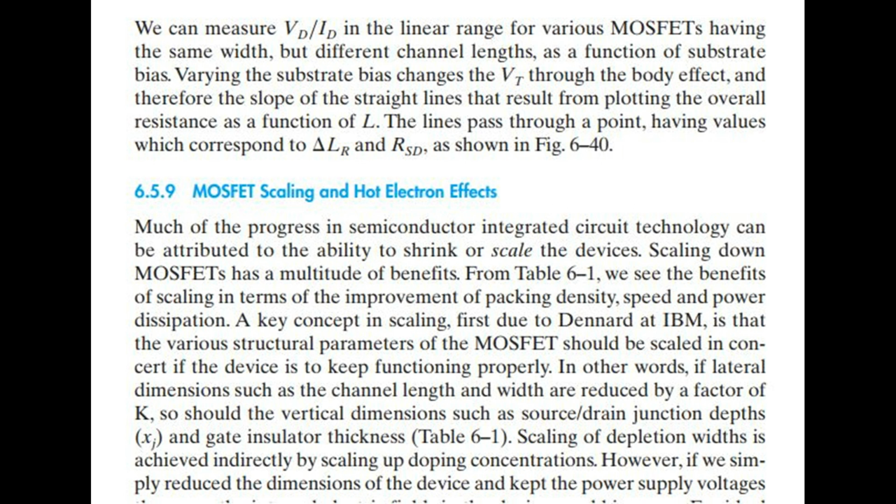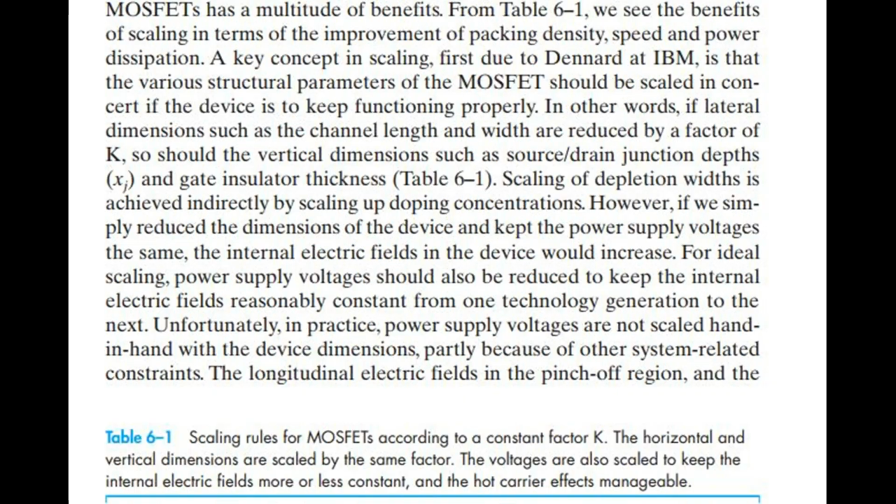In other words, if lateral dimensions such as the channel length and width are reduced by a factor of K, so should the vertical dimensions such as source/drain junction depths, x_j, and gate insulator thickness, Table 6.1. Scaling of depletion widths is achieved indirectly by scaling up doping concentrations. However,